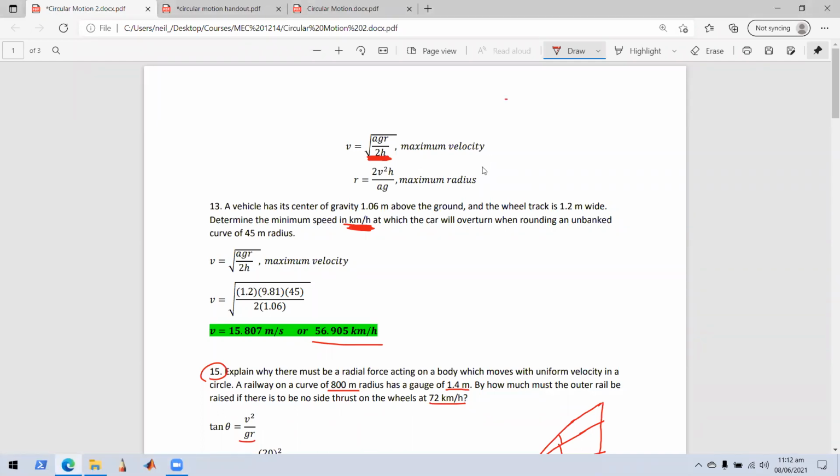Again, moment is just a force applied at some distance. So if the vehicle is higher, if it has a higher center of gravity, then the force is going to be applied on the wheels, and that's going to have a greater moment, causing this vehicle to possibly flip and twist. Doesn't matter which side we put it on, which side you turn the vehicle? No, it doesn't matter, because we assume most vehicles are symmetrical.